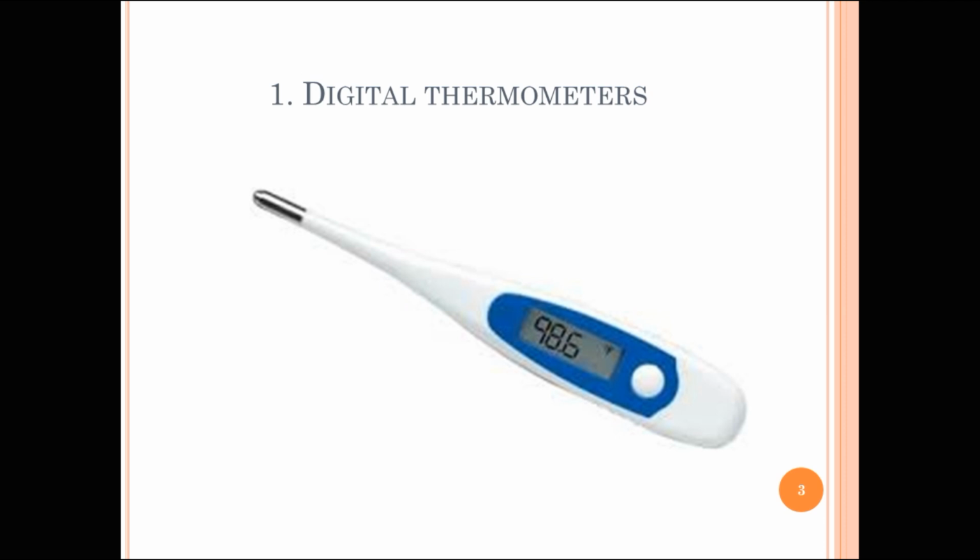Simple units provide linearization for only a single type of thermocouple, whereas linearization with a microprocessor allows switch selection from among 6 types and gives readings in Celsius too. Reference junction compensation in thermocouple thermometers usually uses an isothermal block whose temperature is monitored by a junction semiconductor sensor, which sends this data to the same microprocessor that does the linearization.